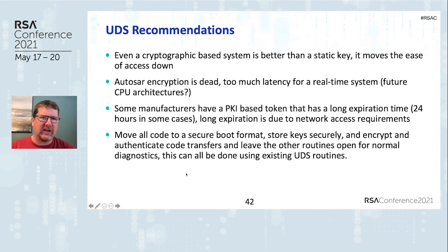The other thing, it's kind of like a standard hardware-based thing, just move all code to a secure boot format, store your root keys securely within the device itself, so it's not on an external flash. Encrypt code transfer. So right now, the hex codes are all sent insecurely.